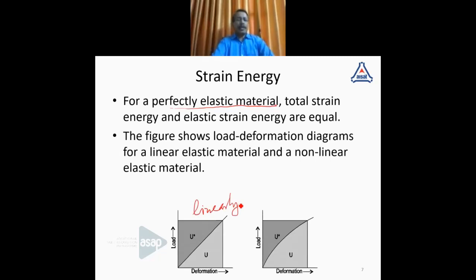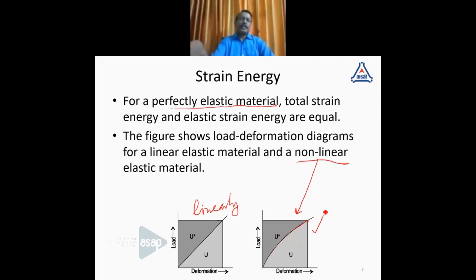This is the load deformation diagram for a linear elastic material, and this is for a non-linear elastic material. That means the curve is not linear. It is not in a straight line. It has a curvature. A non-linear behavior is observed. In both these cases, we can say the material is perfectly elastic. There is no plastic deformation, or we are considering only the elastic part of the deformation. So linear elastic or non-linear elastic, in both the cases, we can have the load deformation curve like this.